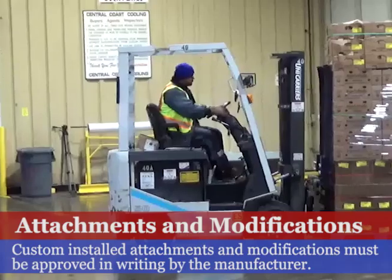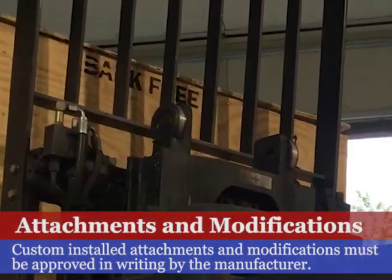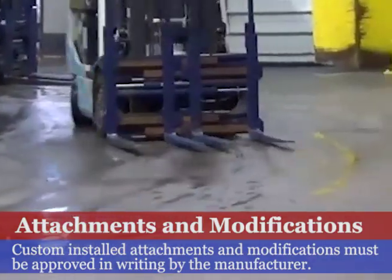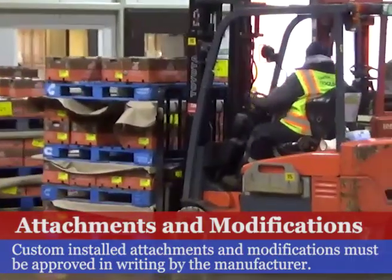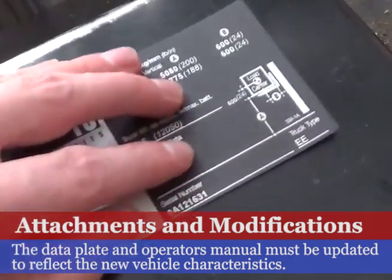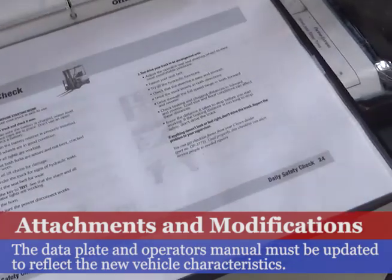There are many different types of attachments that are available for forklifts, such as backrest extensions and multi-pallet forks. If forklift modifications are not factory installed, you must get permission in writing from the manufacturer before it can be used. The nameplate and operating instructions must be updated to reflect the change in capacity and the new operating characteristics of the modified forklift.